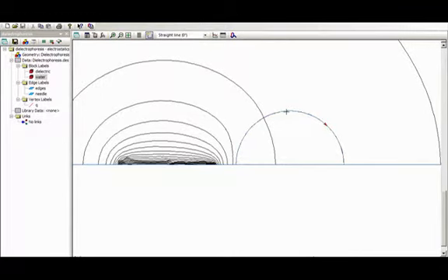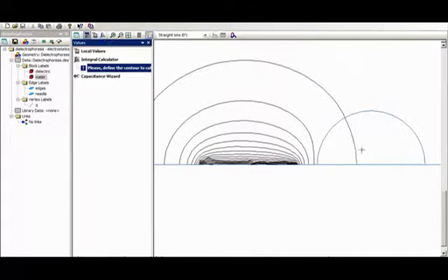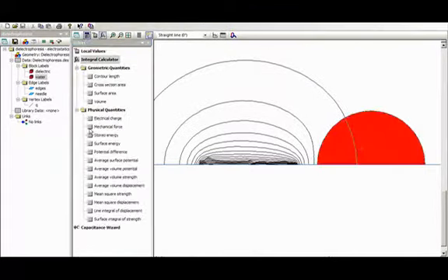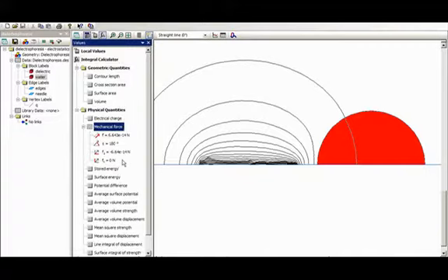and I'm going to surround this with a contour. We're going to look at integral values. We have the integral value tool here, and the mechanical force, which is now in the opposite direction. This is a little bit greater here, -6 times 10 to the -14 newtons, and it's pointing now to the left. It's pointing towards the needle. So the direction of the dielectrophoresis force depends on the relative permittivity of the particle and the medium here.